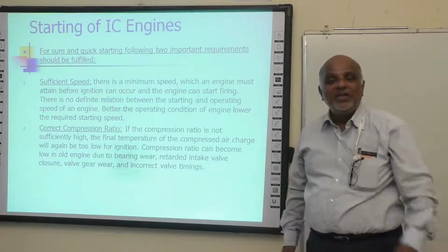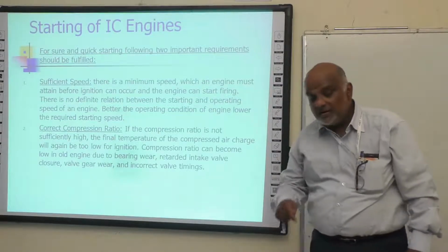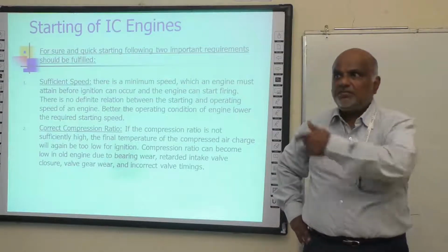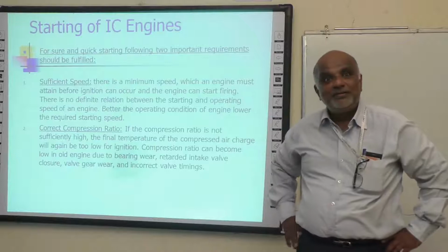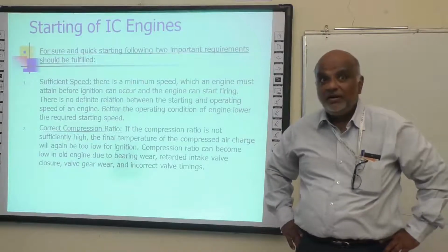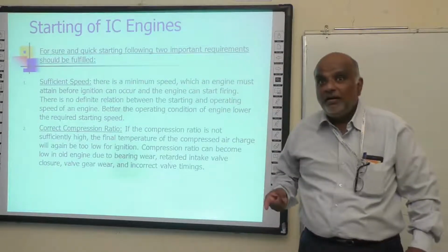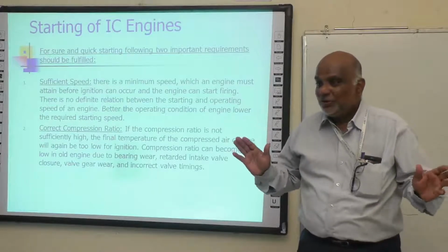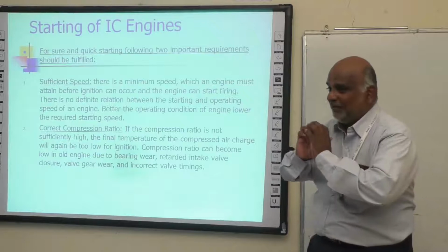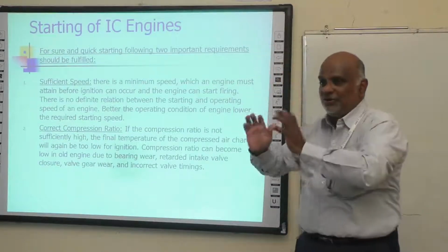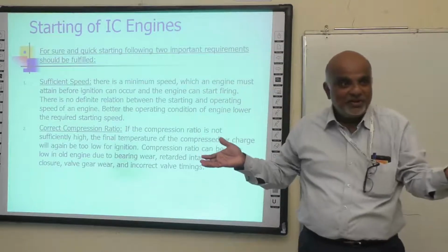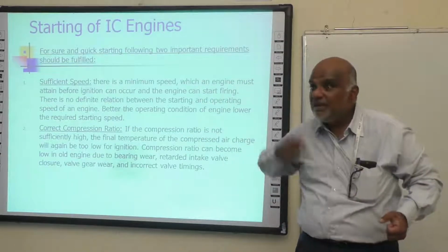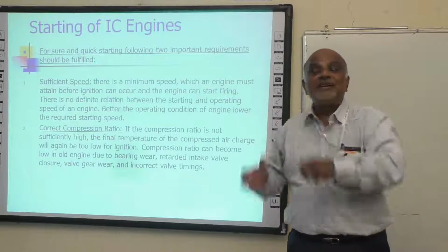That's what you're doing. Okay. Now here in the bike, I said you do a kickstart. Can we adopt the same kickstart in the ship's main engine and make the flywheel rotate? Is it possible? No, it's not possible. You cannot just push a wagon flywheel and turn it with your hand. Such a huge 100 tons weight is a crankshaft. You have to make it rotate, so you have to have a different mechanism.